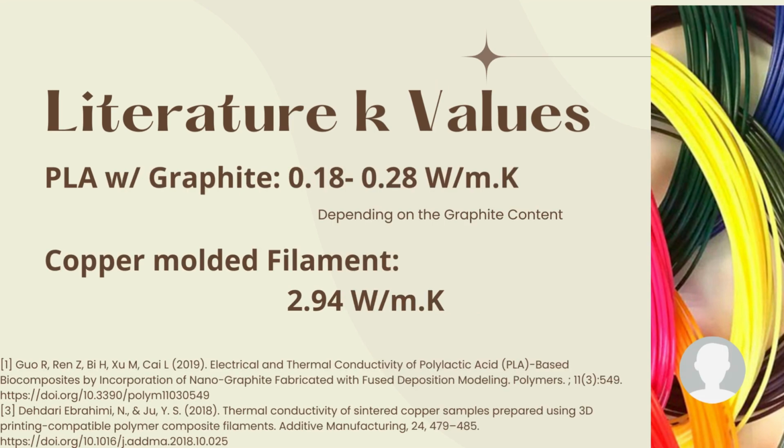Also, Guo finds a range of the thermal conductivity between 0.18 and 0.28 watts per meter Kelvin on the PLA with graphite, and the data characterize different types of copper filaments, finding a thermal conductivity of 2.94 watts per meter Kelvin in a normal molded copper filament.